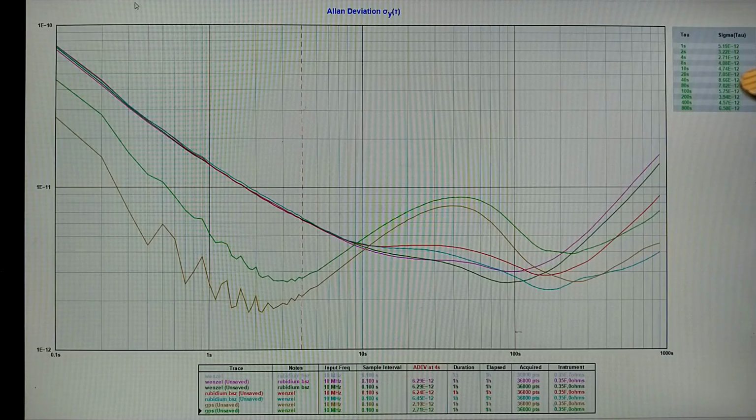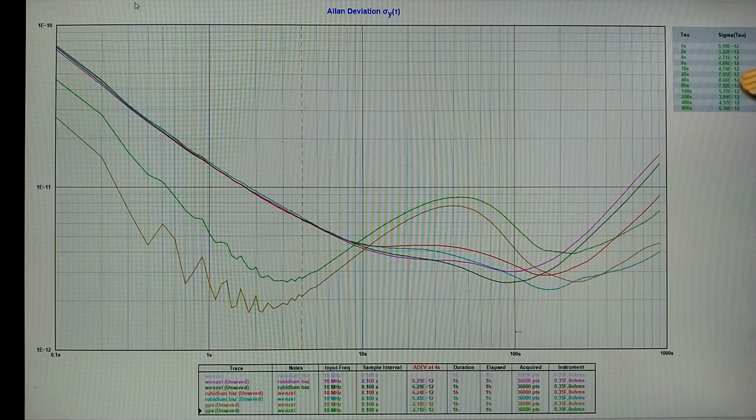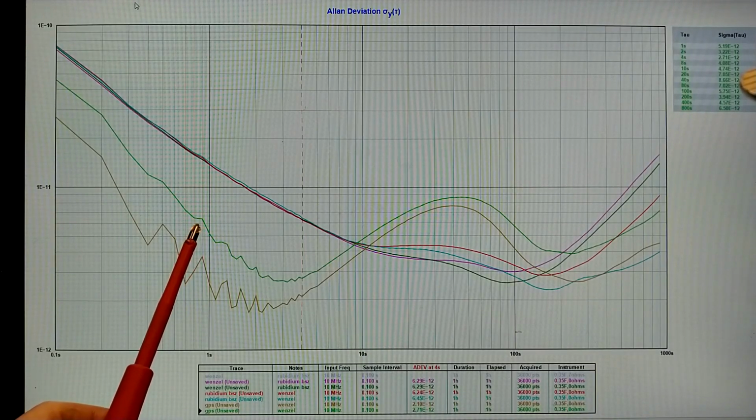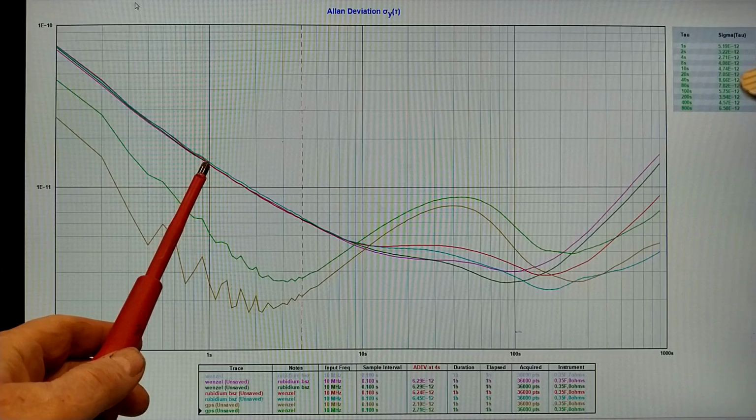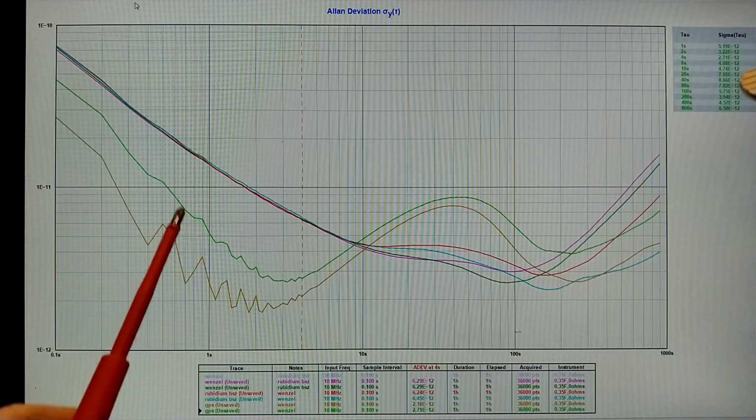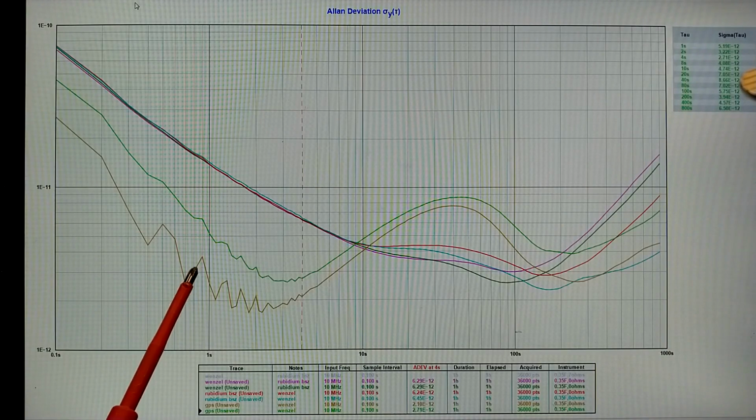I have connected a GPS disciplined oscillator. I know it has much lower sideband noise at 1 Hz offset from the carrier. And here I can see I have 2 traces. They differ more than expected. I don't know why. And here is what I had before, when there was the rubidium controlled oscillator. In both cases measured against the Wenzel oscillator as a reference.